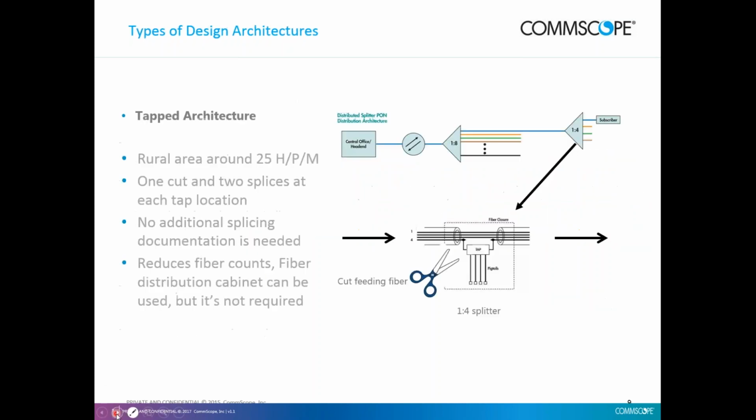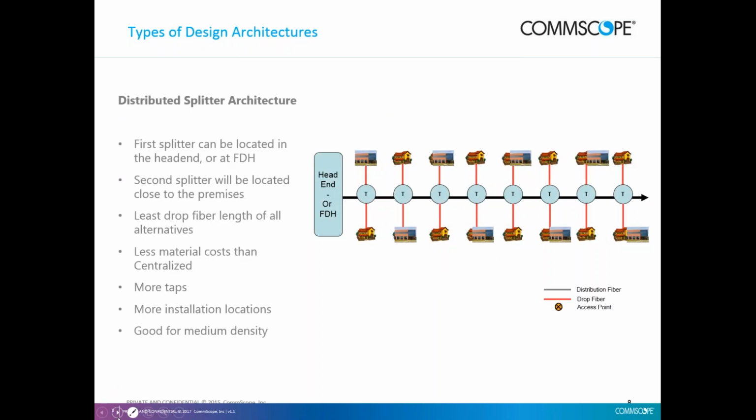So with more taps, more optical passive loss, correct? Well, they'll all be equal. As an example, like I said, if there's more taps, there will be. These aren't, and I should probably back up a little bit. These do say T, which would indicate tap. It's actually a splitter. So I apologize for that. Somebody else's drawing I stole.